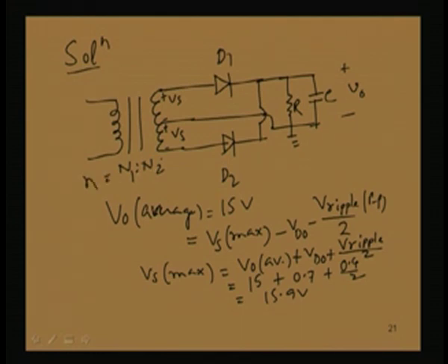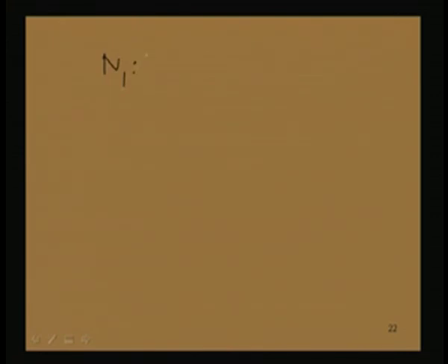Now, for that we must know the RMS value, because for RMS value and peak value, there are generally two ratings defined. So, if you want to find out the transformer ratio N1 is to N2, it is nothing but V input by V in the secondary, whole secondary is having 2 Vs, but both must be either RMS or peak.